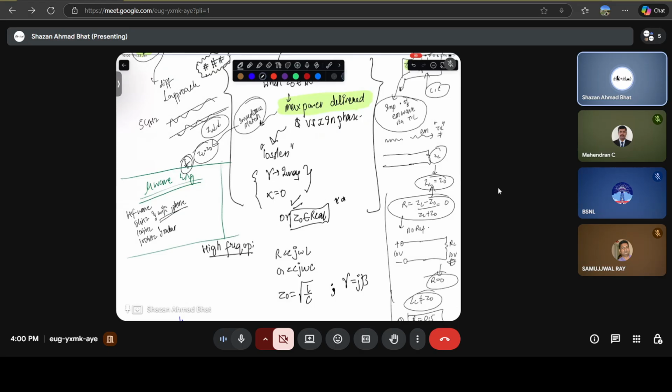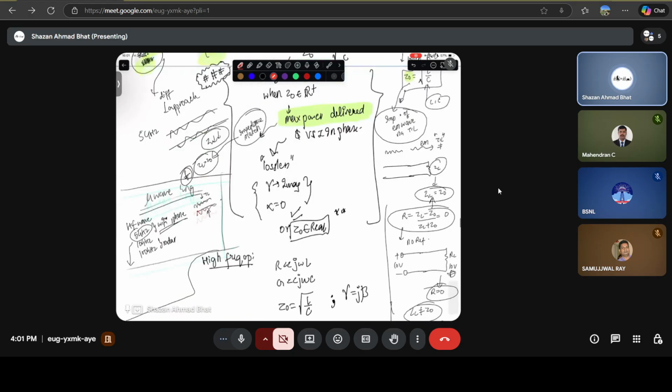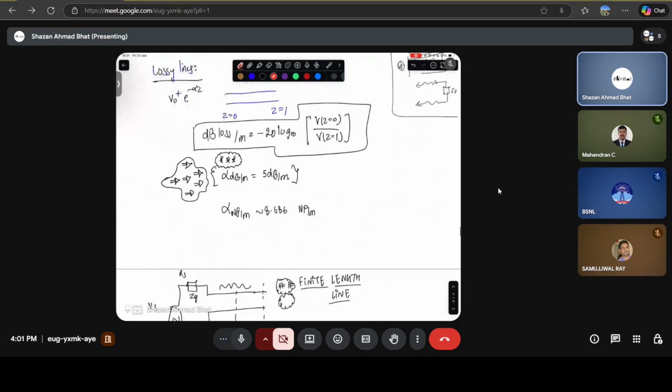They are basically being processed inside your system. The thing is that at the phone level they are not exactly 5 gigahertz because they are down converted. But at the end of the day, you want to transmit certain high frequency. So that's where the microwave engineering part comes into the picture. You design these transmission lines in such a way that they are able to transmit these high frequency signals. That's the part of this characteristic impedance.